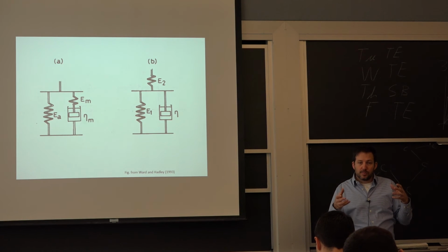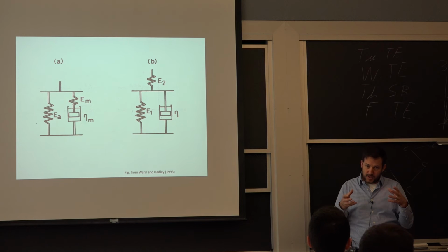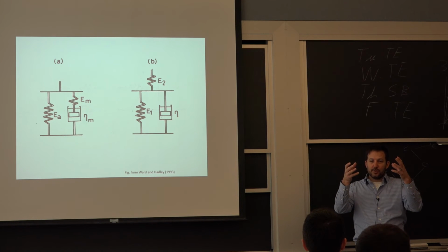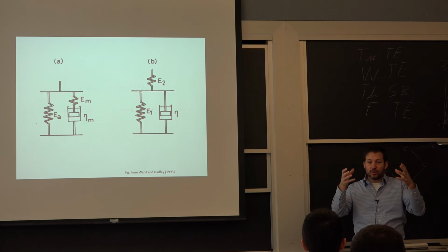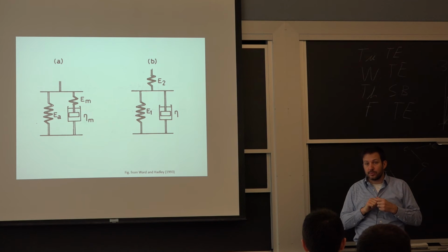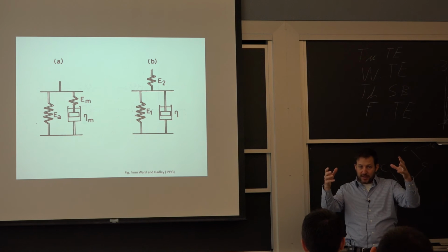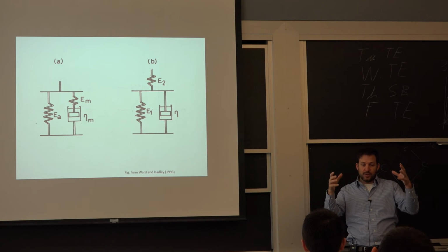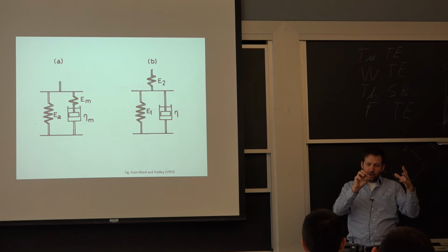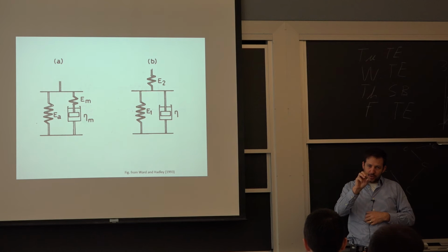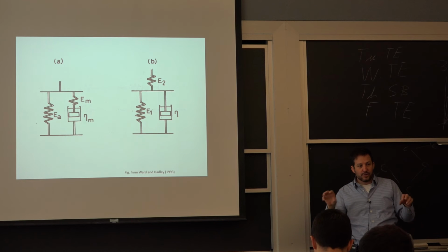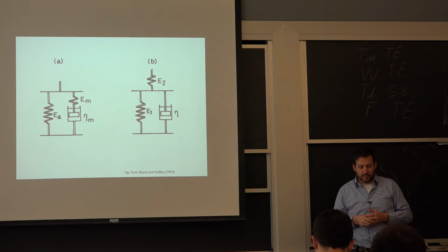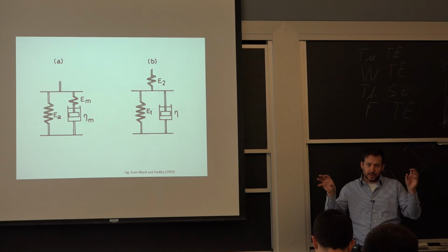A liquid polymer is going to be somewhat viscous, and when you cool it down, the speed at which you're cooling influences when you're going to start forming these crystals. So it's all spaghetti, and then you cool it down. Eventually, you reach a point where there's a local organization starting at nuclei in the spaghetti, and then it just spreads in different directions, a little bit like what we talked about with ice formation or snow. It starts from the middle and goes in different directions.